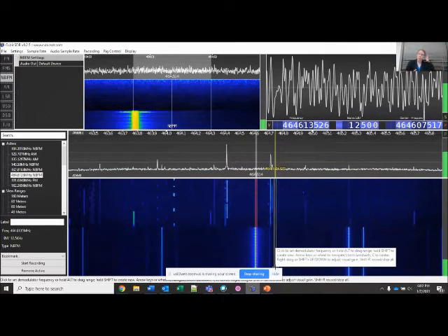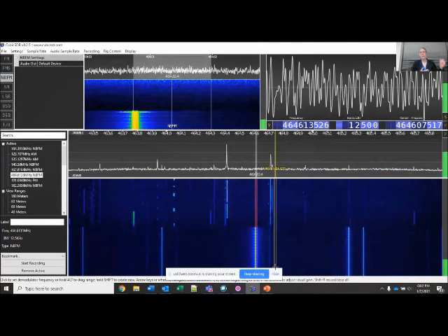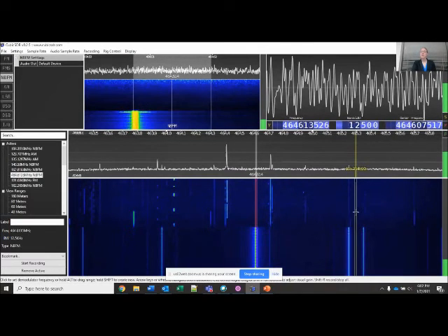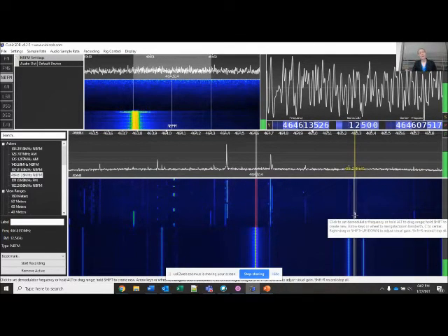For instance, when I was doing troubleshooting with the handheld spectrum analyzer back at Ford, I could easily set that to be showing me everything that it could pick up from, say, 30 megahertz to 300 megahertz and get a really comprehensive sense of what was around me. Here, the maximum bandwidth, I think, is 500 kilohertz. So you do have to do quite a bit more manual sweeping. And again, it's the difference between an $8,000 piece of equipment and a $30 piece of equipment.